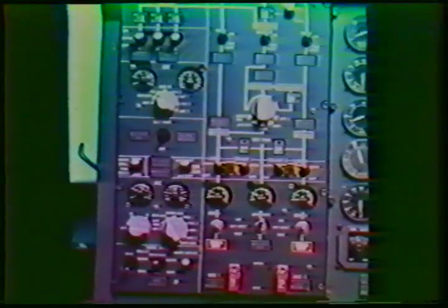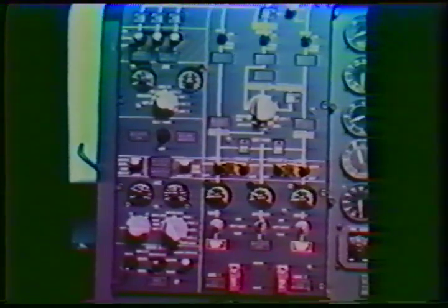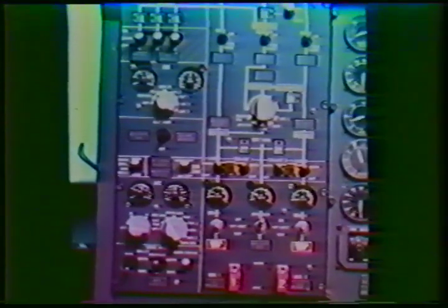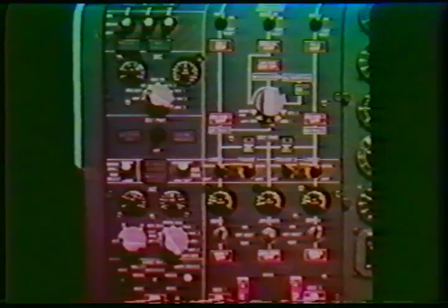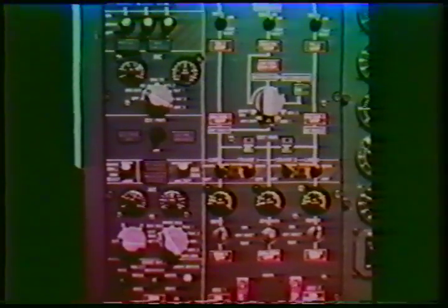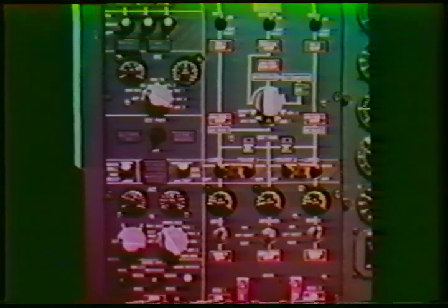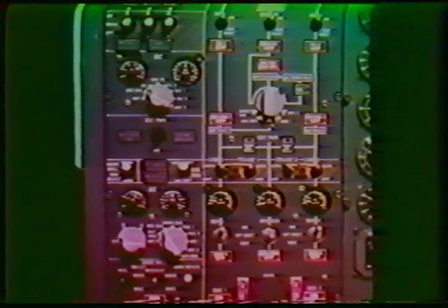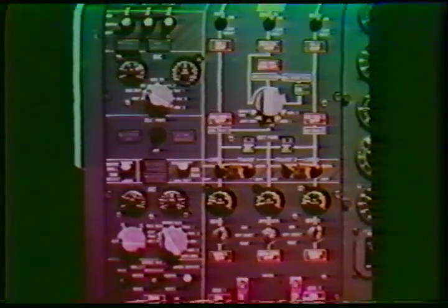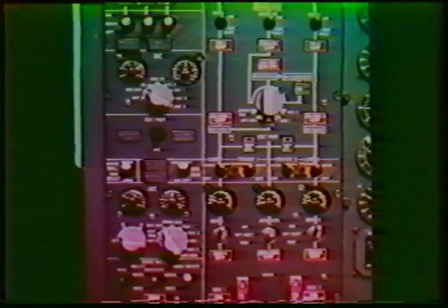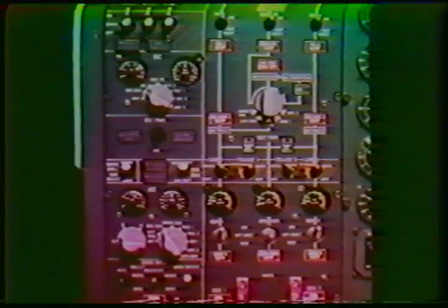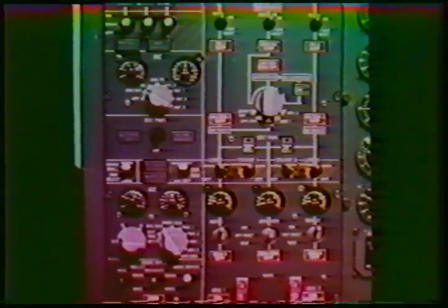Now take a look at the electrical power control panel located at the second officer's station. The flow of the electrical power is schematically engraved in the panel from bottom to top. Before looking closely at the electrical control panel, it is important to know that the illumination of any amber light will be accompanied by the illumination of an amber electric light on the master warning panel and the single-stroke chime.